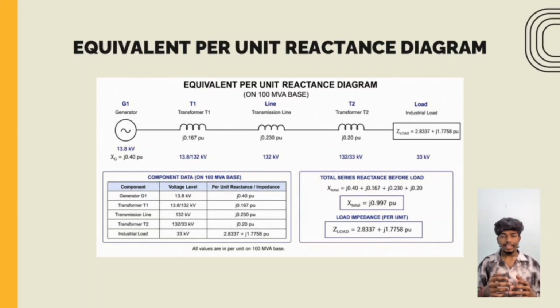Next, for task 11, we determine the equivalent per unit impedance of our industrial plant unit, which draws 30 MVA at a 0.85 lagging power factor. Since it operates right at its rated voltage, which is 33 kV, its operating voltage is perfectly 1 pu.